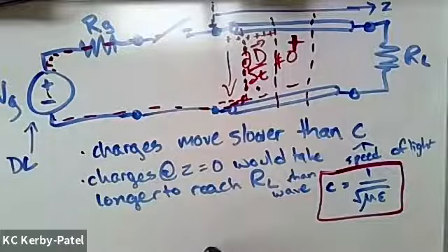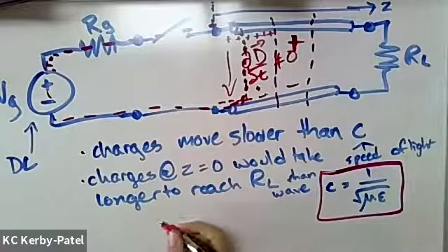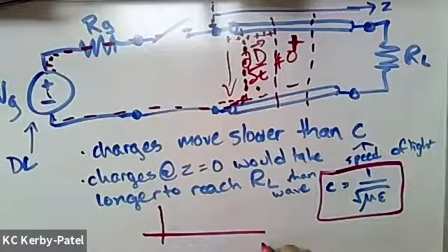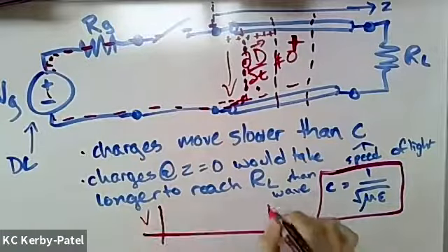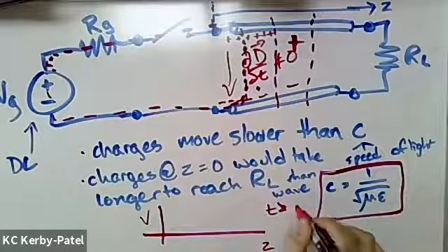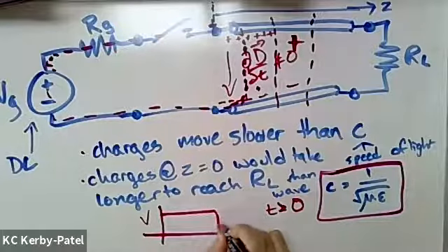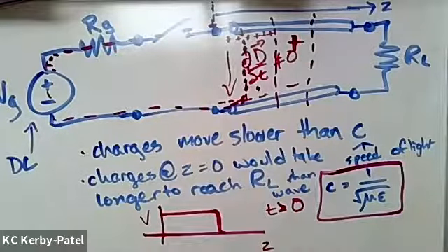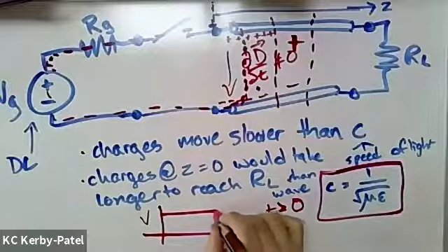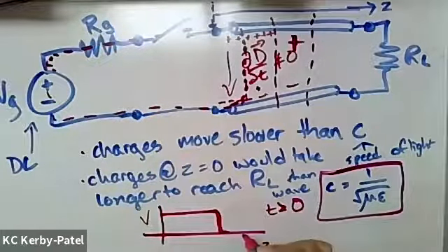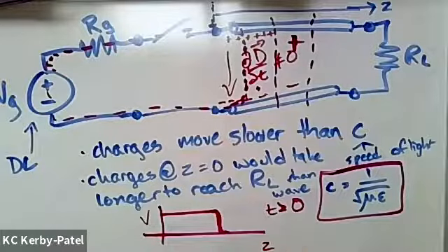So that's what happens. If this is position, and this is voltage at some time greater than the time that we hit the switch, you're going to have a voltage wave that's basically discontinuous. This edge gets rounded out by the fact that the capacitor can't support an instantaneous change in voltage. And then this wavefront moves down the line towards the load.